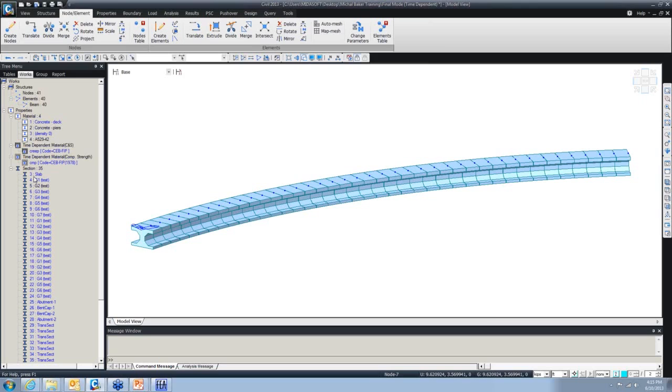Yes, they asked if we are using the grillage model, is it just a combination of line elements or beam elements put together as the same model? Yes, it is, and it makes it so easy to do the design later on, and also so easy to extract the results on those. And as I showed you, you can simply define any tandem profile for all these girders.